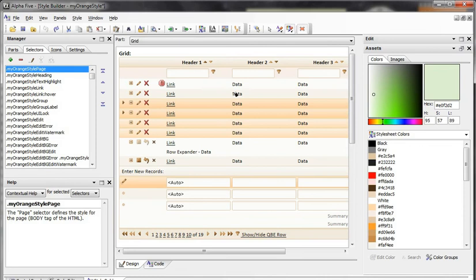Once you have the Asset Tool selected, your environment's going to change, so you have a cursor in design mode which shows a paint bucket. Now if you hold down control, you're going to see that the cursor changes to a picker tool. What this means is that if you're holding down control, it's going to be picking stuff up from the environment, and if you let up on control, it's going to be dropping stuff into the environment from the asset panel. Now it's tied very tightly to what tab you have selected in the asset panel.